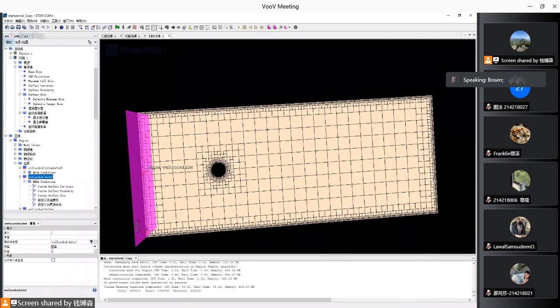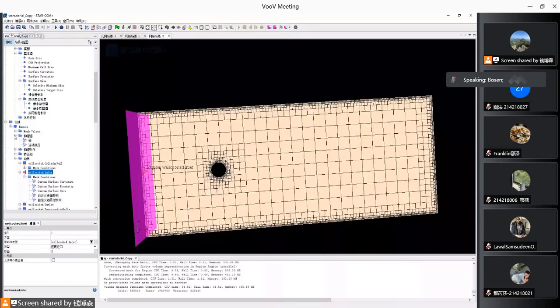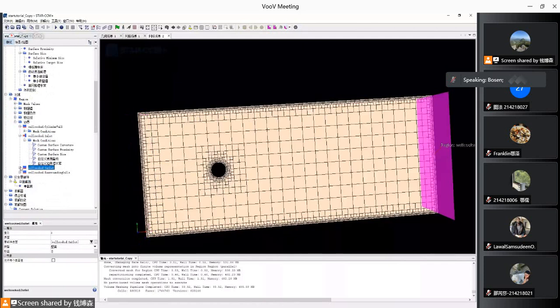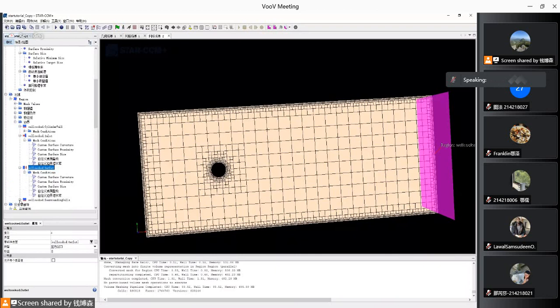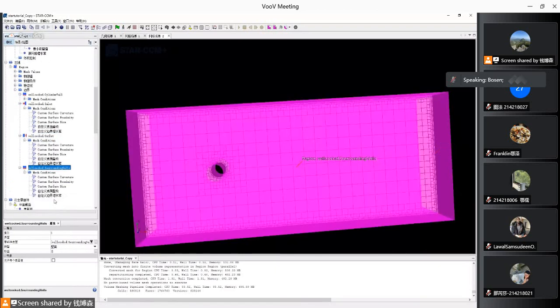So in here, we applied the wall boundary condition, which is not right. So we can change the boundary condition from wall. This is the inlet, so we need to apply it as a velocity inlet. So this is a velocity inlet. Alrighty. And similarly in here, we need to set it as the pressure outlet for the exit. And for here, they are the surrounding walls, mesh conditions.